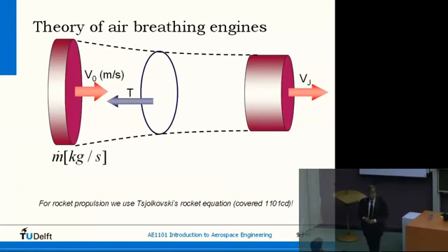But so mass and speed, that's what counts. So we already talked about the speed. At the beginning you have a speed of 0, which comes into the engine. And at the end we have the jet speed that comes out of it, which we jettison. Whether it's a propeller or jet, the principle is the same. The amount of mass is also important, so the amount of air mass that we have through our engine. And those together determine the thrust force that we get.